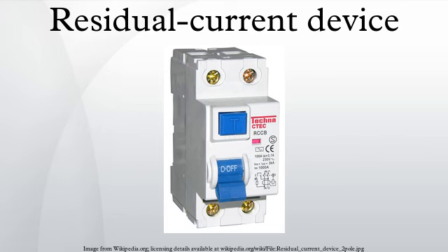Whole installations on a single RCD, common in older installations in the UK, are prone to nuisance trips that can cause secondary safety problems with loss of lighting and defrosting of food. Frequently the trips are caused by deteriorating insulation on heater elements such as water heaters and cooker elements or rings. Although regarded as a nuisance, the fault is with the deteriorated element and not the RCD. Replacement of the offending element will resolve the problem. Replacing the RCD will not.